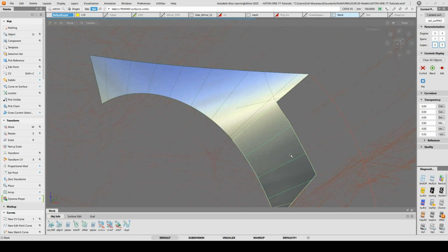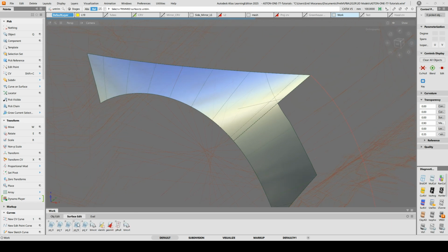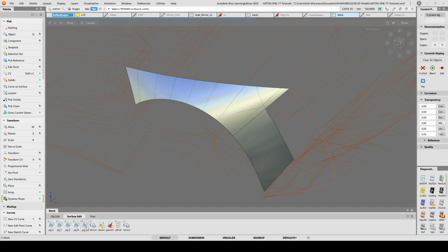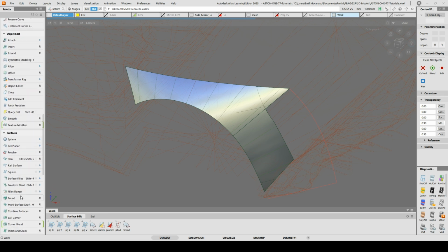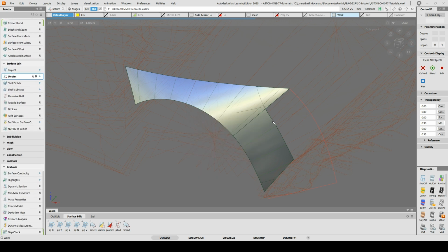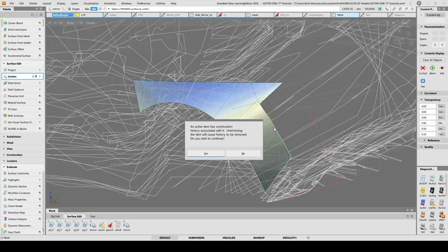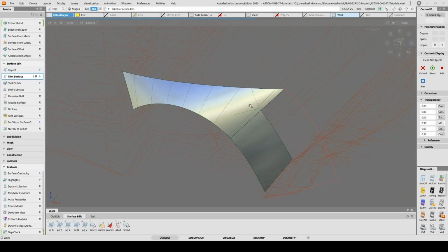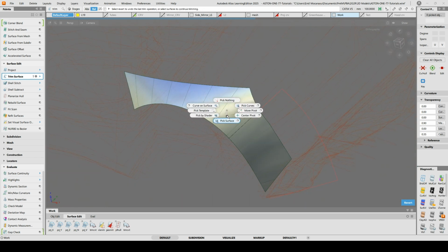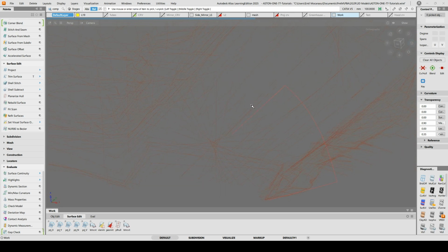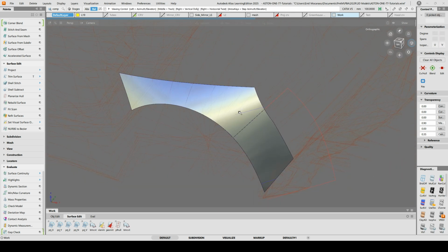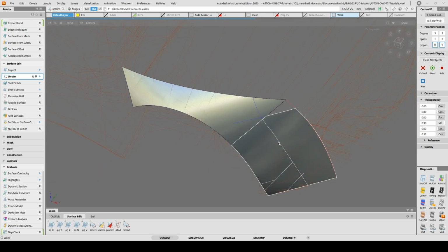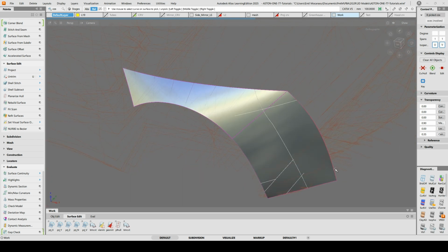Let's untrim this surface, this one. Sorry, got lost in my thoughts there. So I'll untrim this last bit here. I don't want to lose the construction history on that, so what I'll do, I'll take these two surfaces. Let's trim this back. Because what I want to do is take these two, template them, and copy paste new ones in there. And what I'll do is just CV massaging, because I don't want to ruin all of that. So I'll take away these curves on surface, as we don't need them.